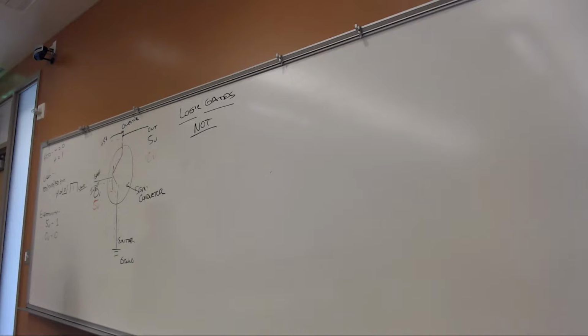As I give you information about the different logic gates, I'm going to give you the diagram. So if we looked at a schematic of a computer, you could see the different gates that are being used in that device. I'm also going to give you the Boolean logic for it. There's this guy named George Boole who created a whole field of mathematics called Boolean algebra, which enables us to be able to create these different diagrams. All of the anding and oring that we do in programming is founded around this. And then the last thing I want to do is give you the truth table.